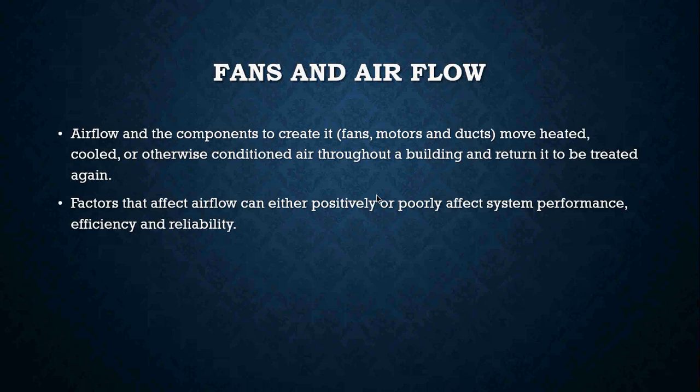airflow in a unit. It could be positively affected, it could be poorly affected, so we have to look at the ductwork. We've got to look at our blowers to make sure that they're clean. We've got to make sure they're flowing in the right direction, not flowing backwards, or that the blower wheel is actually installed backwards, which I've seen.